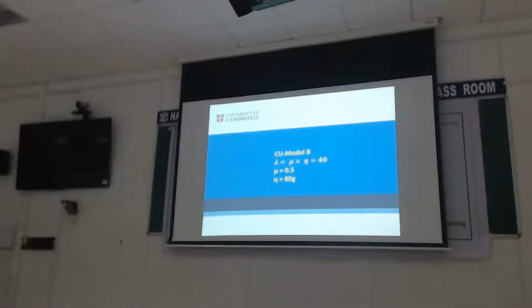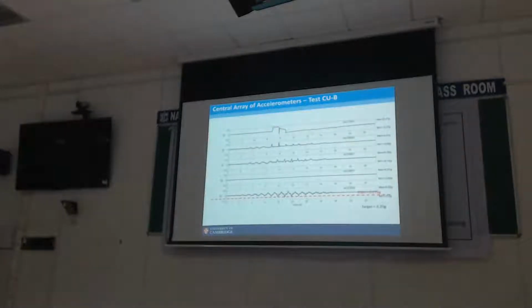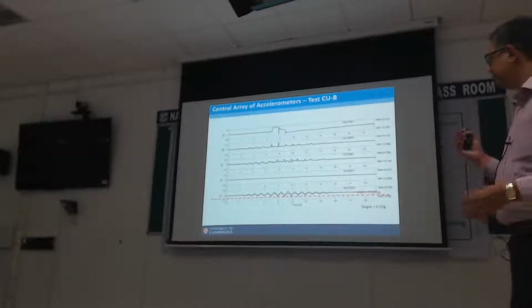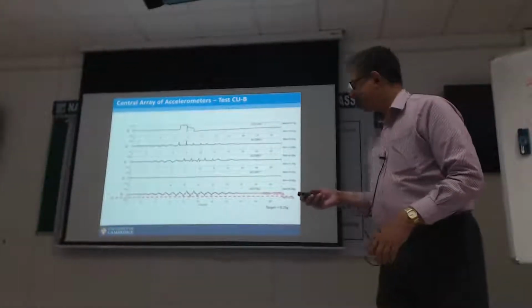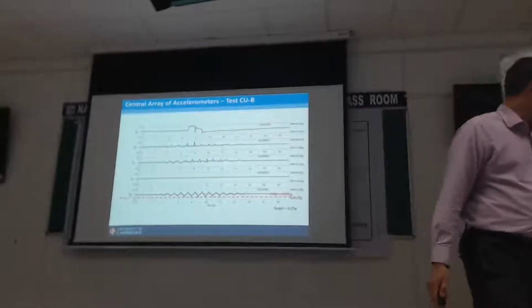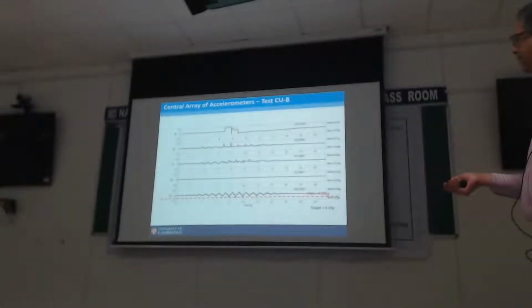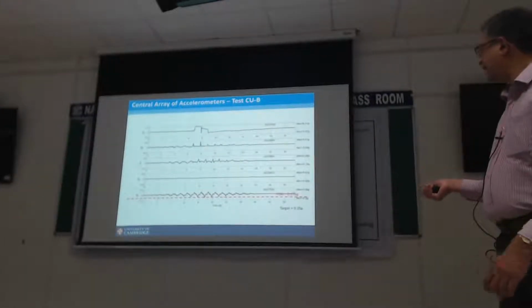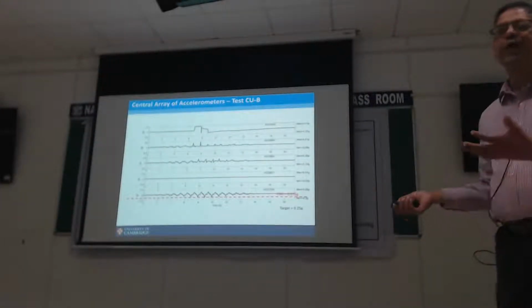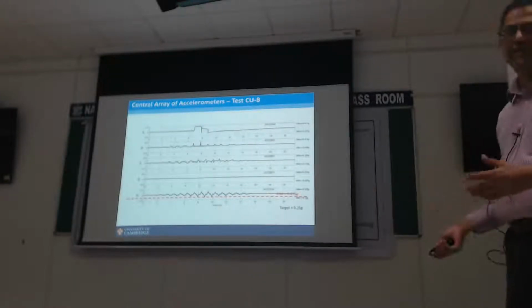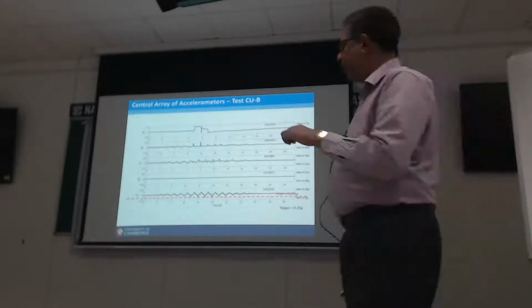Acceleration response first for the ATG model. And as I said, these motions were prescribed, which are common for everybody. So if I prescribe a displacement like that, the acceleration for our shaker came something like this. And we were asked to do 0.25 G, and we can't. We ended up getting 0.276 G, which is close enough.